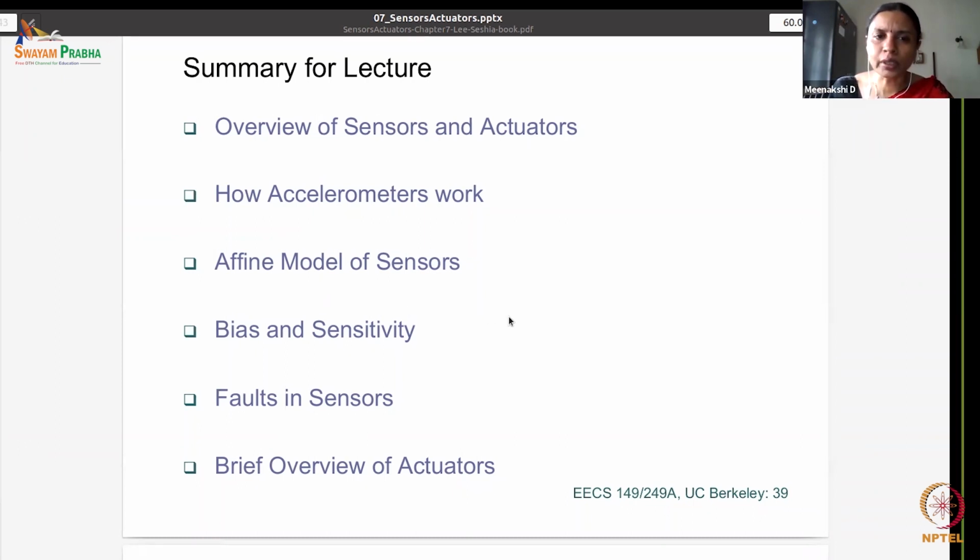So here is how a typical interrupt works. To handle interrupts, programmers write what we call ISRs, interrupt service routines. Even though the word indicates that it could be an error, please remember that an interrupt is not always an error. It could just be something simple like waiting for a sporadic sensor input to come.